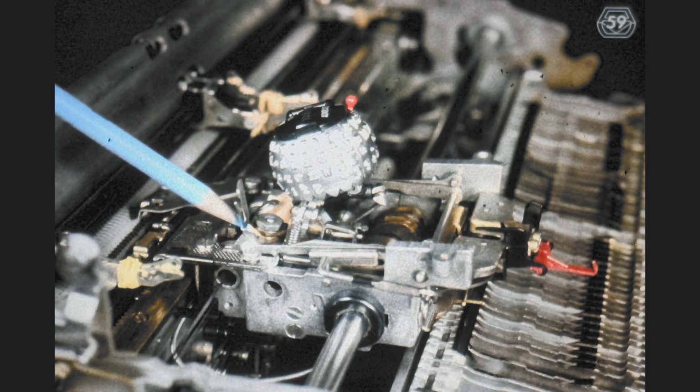Now, depending on whether we had an excessive clearance or a lack of clearance, we move the cam to the left or to the right accordingly. The screwdriver also lets us change the position of the cam in very small increments.